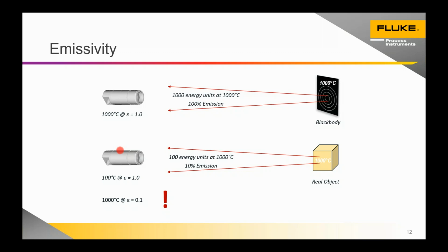It doesn't improve the accuracy, but it does mean that you can rely on the fact that you know where you're measuring from. There's an inverse to that: if you do get too close to an object and it's very hot, you can influence the reading in terms of heating up the detector and causing thermal shock in the unit. And then there are some applications where you can essentially increase emissivity by using gold reflectors, but you have to then be very close. But generally, no, you don't need to be close. There's no improvement from being close up.